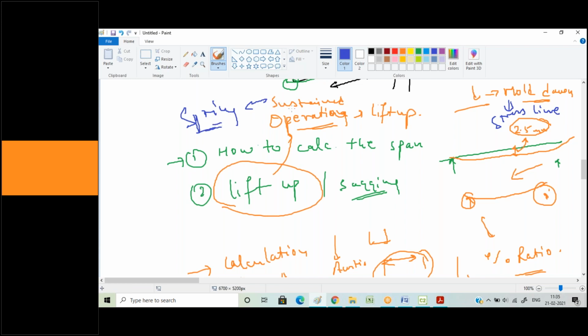If there is room to increase the stress and it is within the permissible limits, obviously you can increase the stress and put a hold down support. But if your line is not permitting that, the only option left for you is springs. So you will only use springs for that.